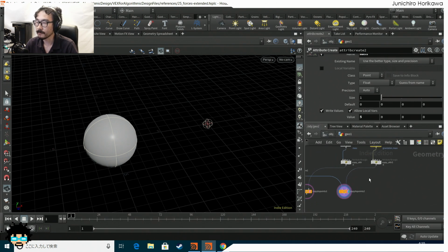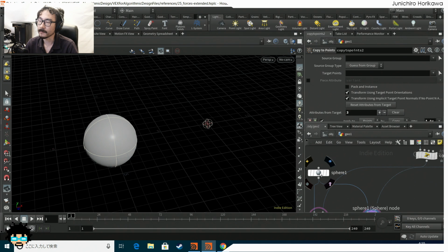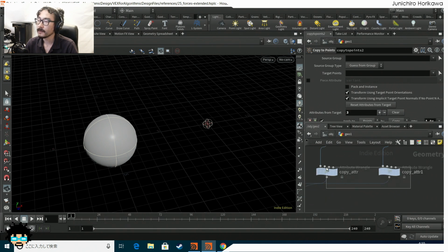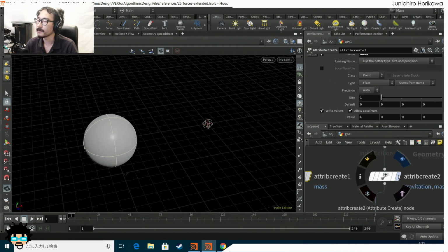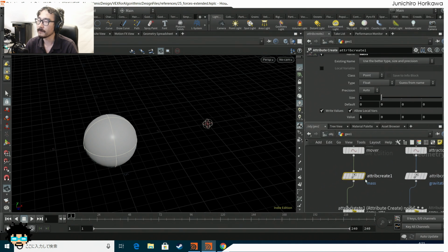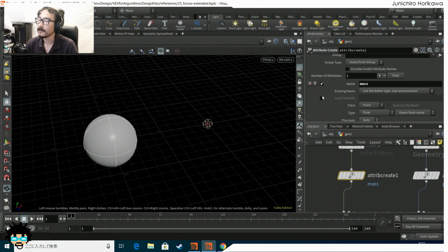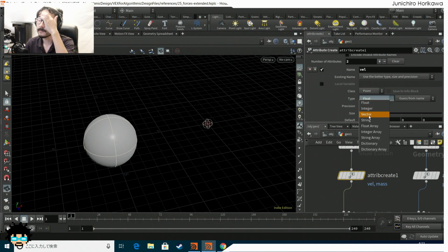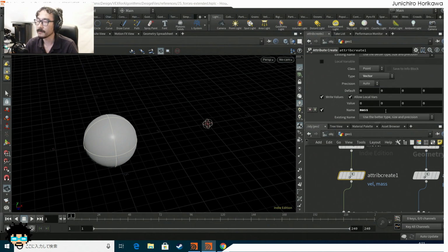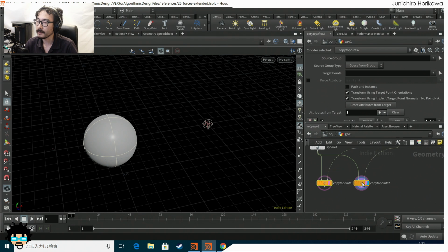Now since we are creating a force and I want to show you as an animation, we're going to use a solver in order to calculate the force at each frame and move the object using its velocity. So we also need a velocity value, not for each object, since the attractor in this case doesn't move. So I'm only going to move the mover object, and I'm going to create the velocity attribute just for this mover object. Let's call this vel. In this case, it has to be a vector value. I'm going to start with 0, 0, 0.